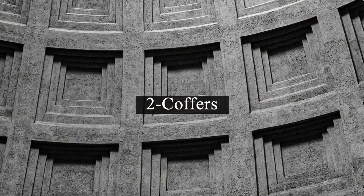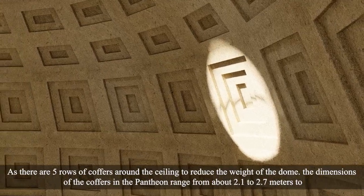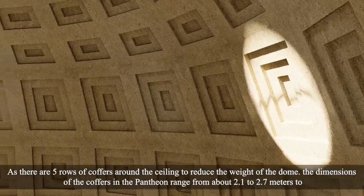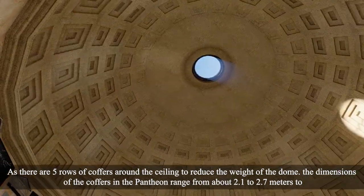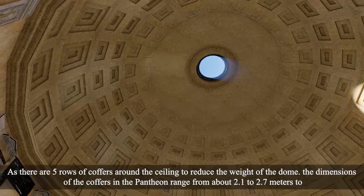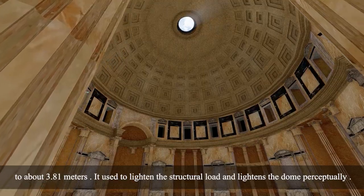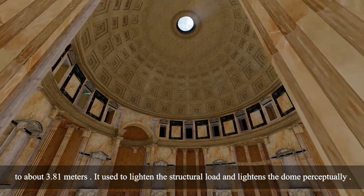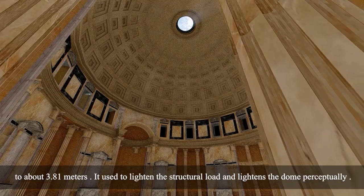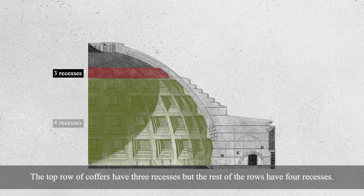Second, coffers. There are 5 rows of coffers around the ceiling to reduce the weight of the dome. The dimensions of the coffers in the Pantheon range from about 2.1 to 2.7 meters to about 3.81 meters. They are used to lighten the structural load and lighten the dome perceptually. The top row of coffers has 3 recesses, but the rest of the rows have 4 recesses.